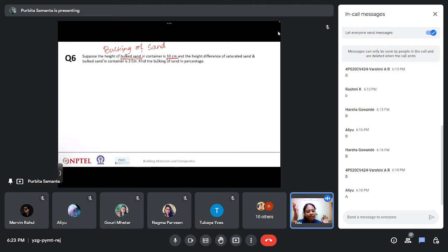For x amount of bulking of sand, there will be a significant reduction in the quantity of concrete produced. These things are not desirable. The mix of these different raw materials is very important, because you can see how change of proportion can change the strength that is ultimately gained.